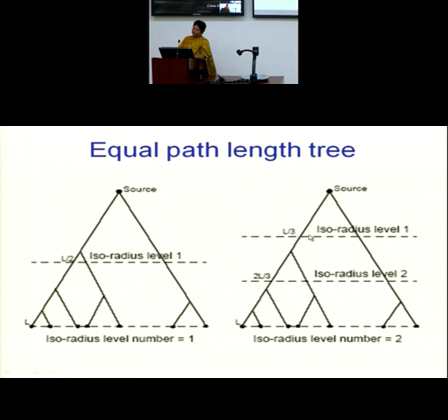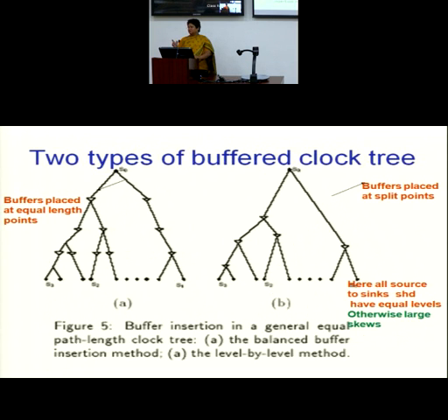Now whenever you put a buffer here, that means I need to design this segment, and I need to design the buffer here, and the buffer also here. So we need to see the designing of a buffer and the designing of the segment length, so that skews between any two destinations, from here to here, here to here, they should be within the maximum value permissible. Buffer design we will come to a little later, but everything is guided by the skew limit. What's the maximum permissible skew?